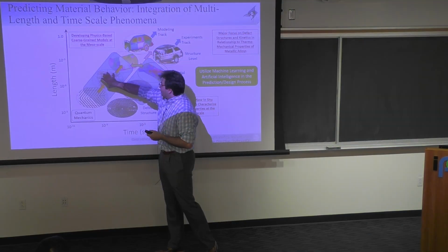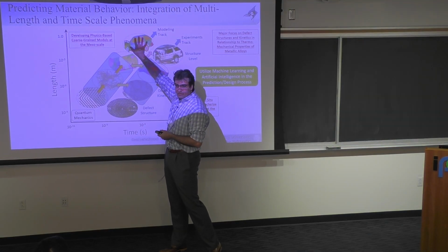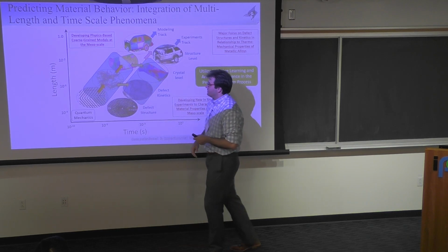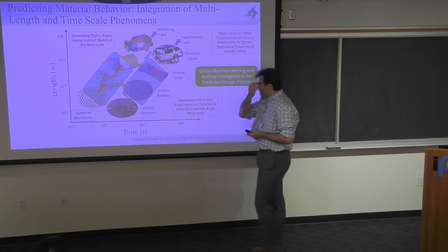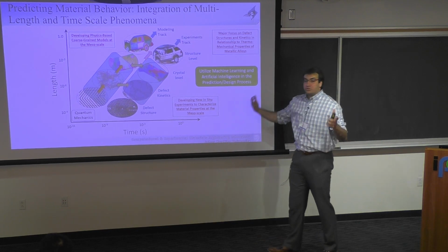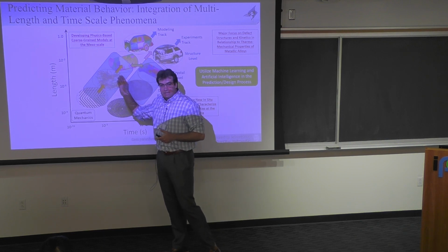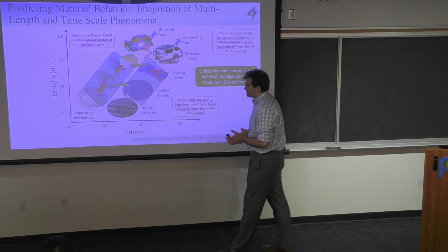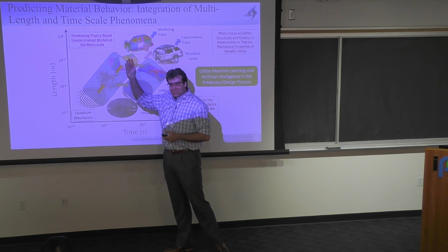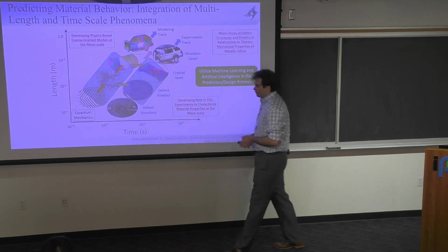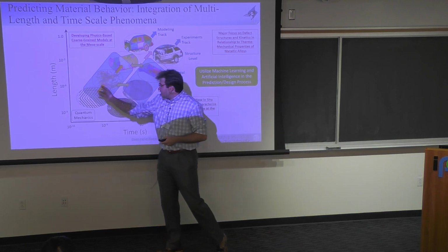But finally, the end goal is when you get this information, that doesn't tell you anything about the part over there. It can tell you local properties, but ultimately you need some type of intermediate tool that allows you to be able to go to multiple grains. You look at sample size, and that is beyond the capabilities of these coarse grain approaches. So we need to be able to input information into crystal plasticity models such that we can get into the coarse grain level. So this is precisely what I'm going to be talking about today.